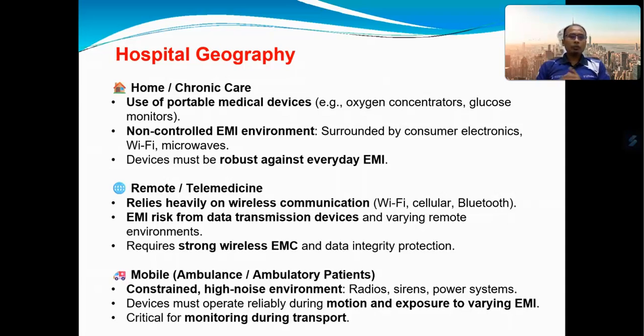All right. Now we move to the next environment, which is the remote or telemedicine. In this area, the medical device relies heavily on wireless communication, such as Wi-Fi, cellular, and also Bluetooth connections. So there is EMI risk from data transmission devices and also varying remote environments. This kind of medical device requires strong wireless EMC and data integrity.